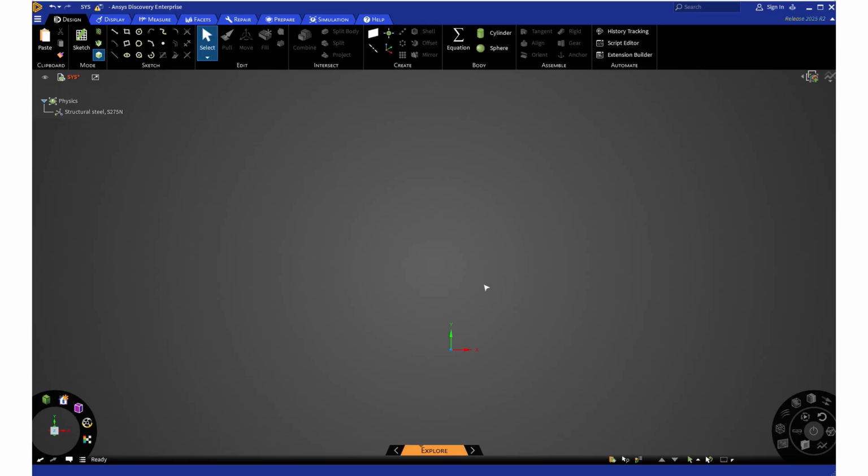Now we're ready to start to sketch, and it's often good to see the sketch plane. So if you click on sketch mode in the sketch plane, you can see these sketch planes. For this model, I am going to switch sketch planes. Then I'll sketch the cross section, and then I'll rotate it about the Z axis. So you can see as I move my cursor around that the sketch plane is changing planes. So I'm going to click on the XZ plane, and then when I go to rotate it, I can rotate it about the Z axis.